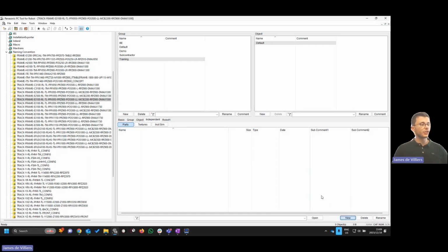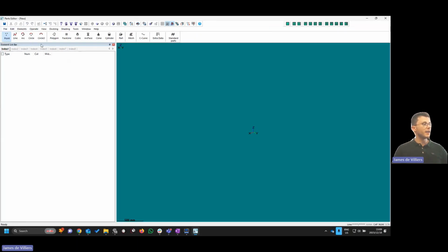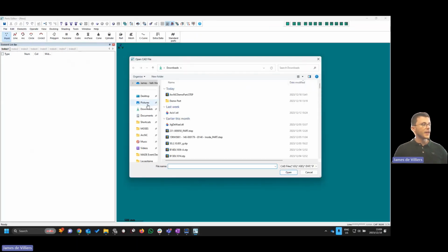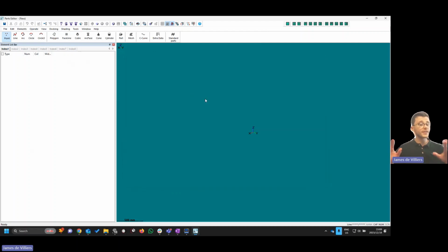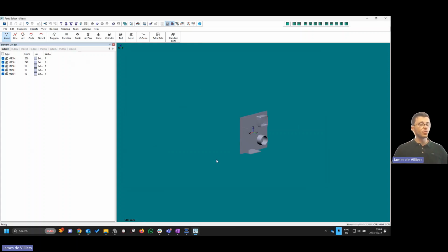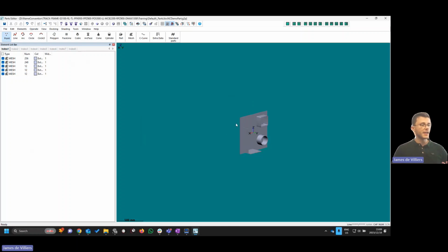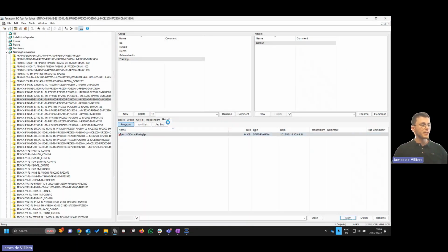I'm going to click on new, and we will create a new part window over here, and I will simply say file, import CAD file, and then under the exact same part over here, I'll upload the same step file. It's important that you upload the same step file and you do not manipulate its position. So I'll click save, and it will become clear in a second why we do not manipulate its position. And now we have a part in the independent folder.